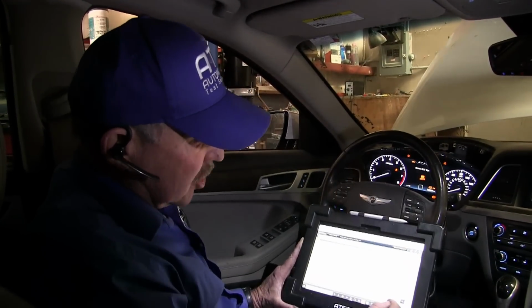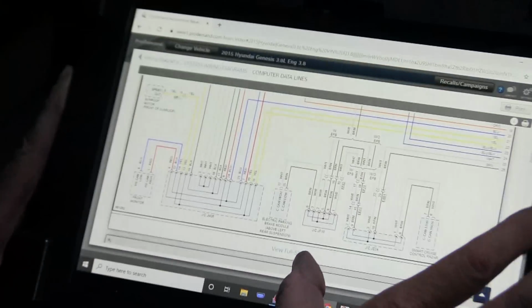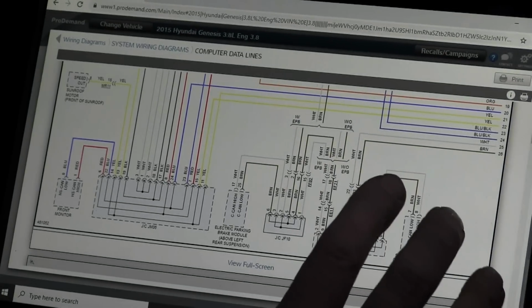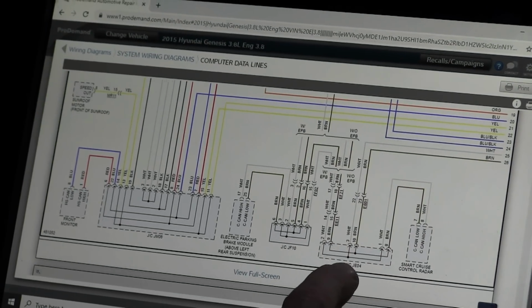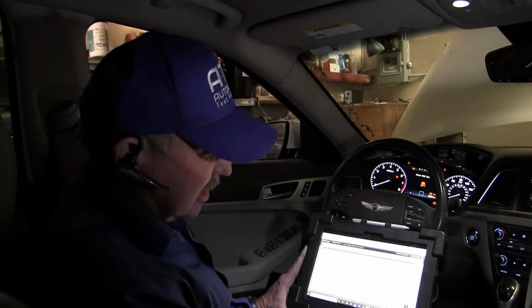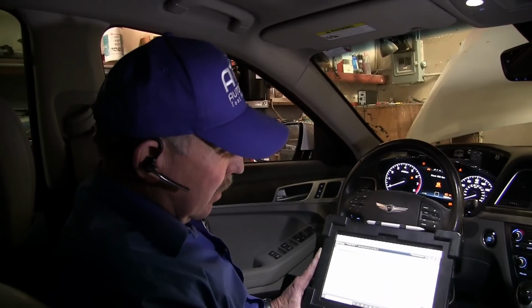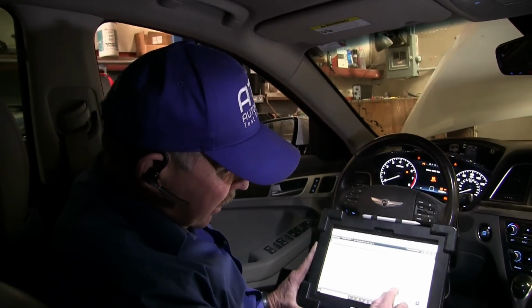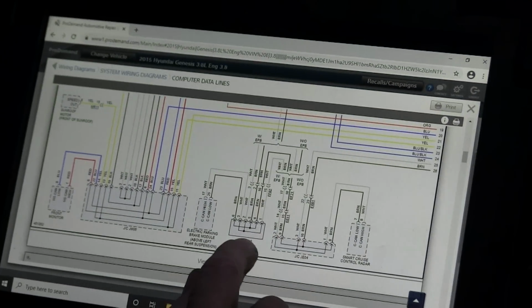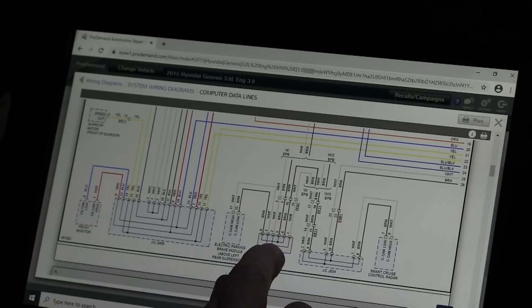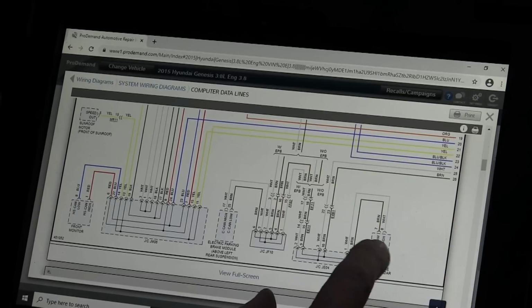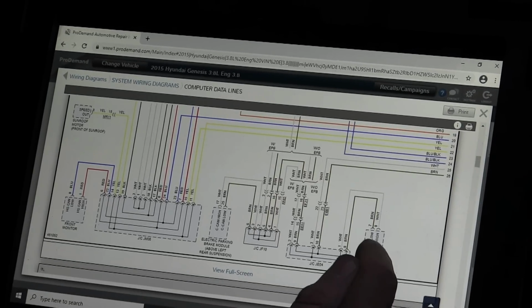Now we're on the dash, and the dash is way down in the system. So now, I want to plug that in, and I want to make sure my bus fails again. And once it fails, then I want to try to disconnect this smart cruise in the front just because it was hit in the front. And then, since this one goes back and feeds a big portion of the bus, I need to find this one, this JF10. So if I unplug this, and the bus is still down, if it comes up, that's what's wrong, and it was hit in the front.